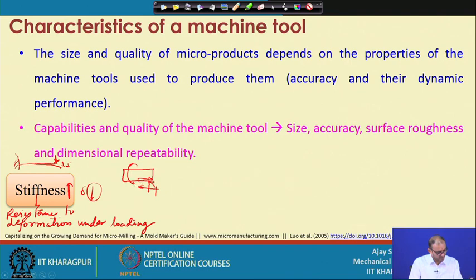So, this much physical resistance is also provided by the workpiece, and the tool is also providing enough force. So, under this particular condition, how much is the stiffness? Suppose you want to move from here to here, whether you are cutting exactly in the same direction or your workpiece is bent in this direction, and sometimes the tool is also coming out of this direction. So, that is decided by the stiffness of the different components of the machine tool.